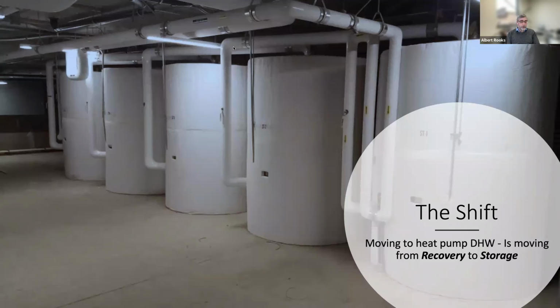The biggest change that we're going through with multifamily domestic hot water is a shift from high recovery rates, where you'd have a really strong gas boiler. We'd size it in some number of MBTUs so that instantaneously we can create a whole lot of heat, transfer that heat onto water, and then give it to the building. Because we can bring in a big pipe of gas, light it on fire, put it under a water vessel, and efficiently lift the water temperature quite quickly, we don't really need a lot of storage.